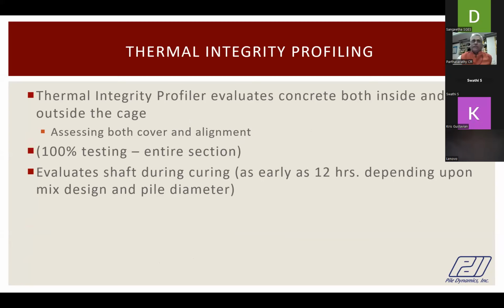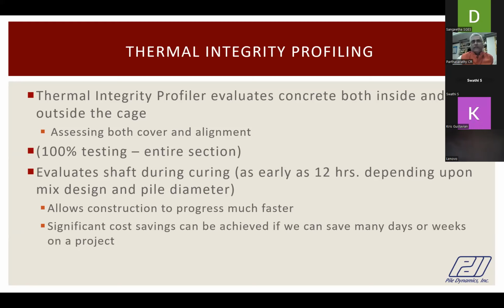Unlike your CSL, you are only testing within the reinforcement. This method evaluates the shaft during the curing process as early as 12 hours, depending on the mix design and the pile diameter, and allows construction to progress much faster. Significant cost savings can be achieved if we can save many days or weeks on a project.